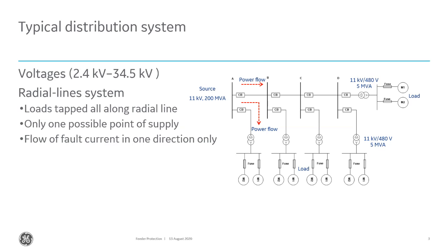And the beauty of the distribution system is that mostly, and not all the time, there's usually one source, which is usually the utility substation. There might be cases internally in some facilities that have cogen, and that's a different scenario. That's why we can apply overcurrent protection, because overcurrent protection is inherently non-directional by nature, and because most of our distribution system has power flowing in only one direction, it's easy to apply overcurrent protection.